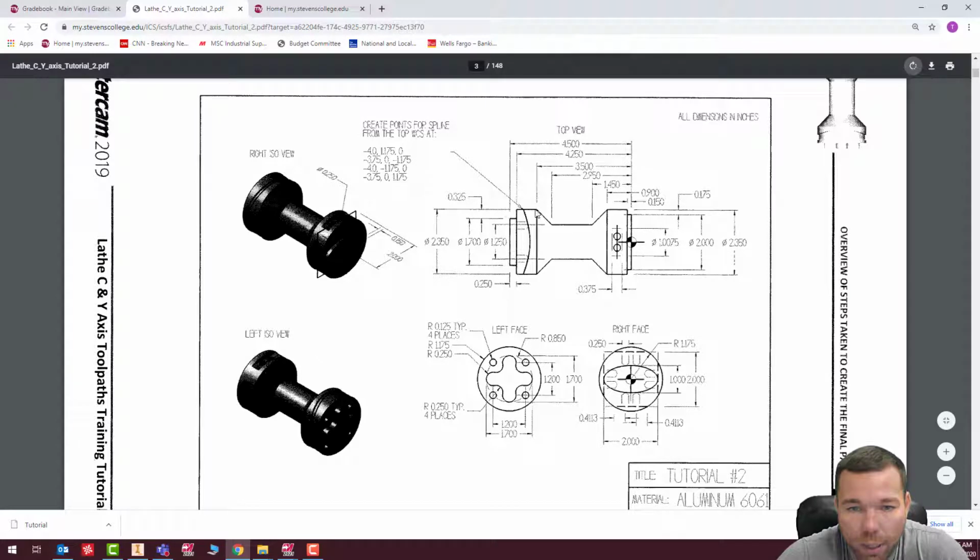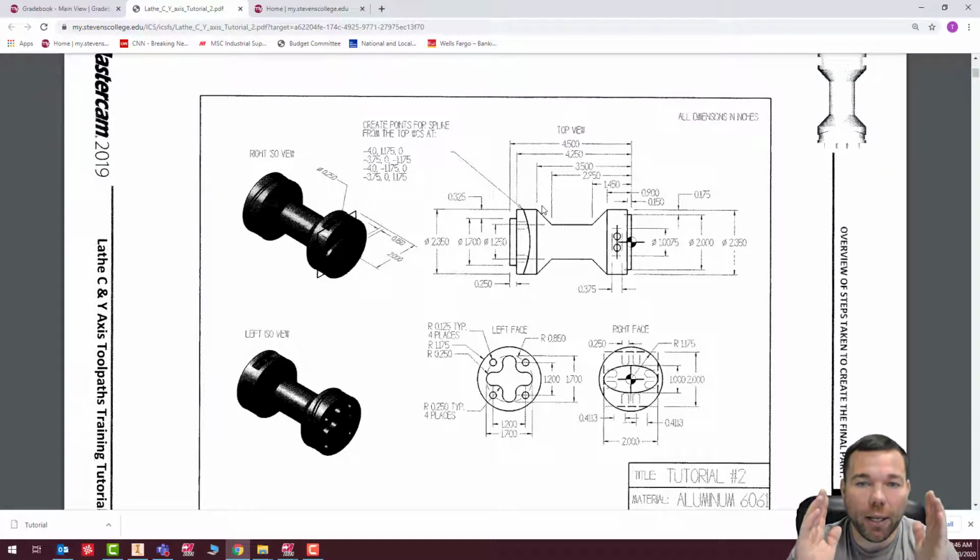I'm probably going to put a bit of a margin on the back side here. But I'm going to pretend like this is a slug. So I'm slugging this out, maybe give myself like a 4 3/4 inch slug. Hold on to this section and then do all the work up to this point. And then grab it with the sub spindle and then do all this work on the back side. So that is my plan right now.